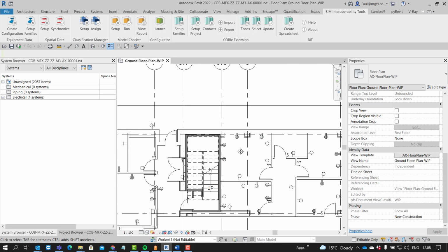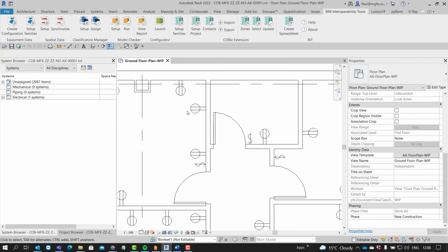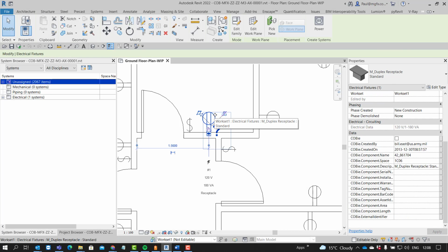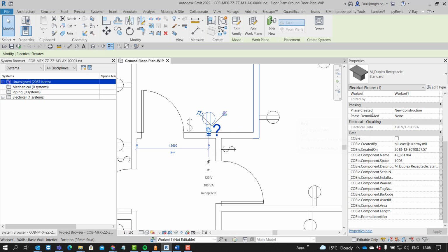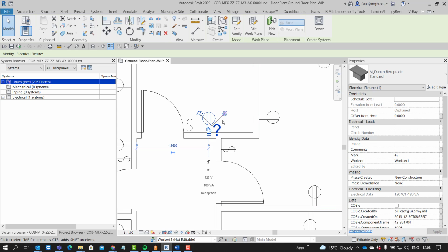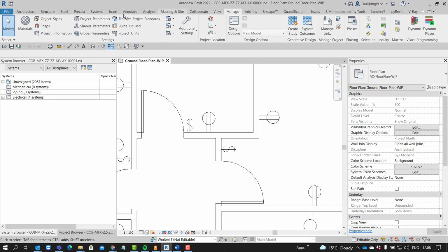So it's very important to apply standards to the project, and typically any information that you add to the project. So, for argument's sake, if there is a component and you want that component serviced, and you see that in the information there's nothing here that says that you must service that component on a specific date or when it was serviced, then you would go to the project parameters and add that parameter to the project.